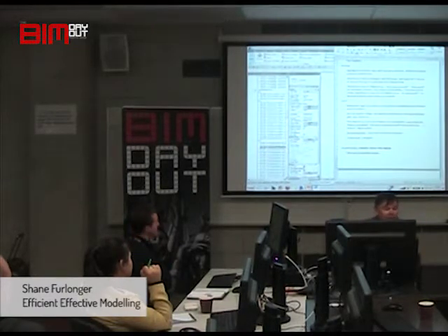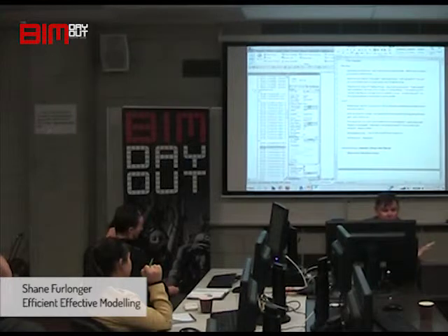So yeah, unconnected, know what it means if you're going to use it, and that's about the only time I do use it. When I know a wall has to be a certain height, and it doesn't matter whether I'm going to offset it down or up. I want it to stay that particular height.